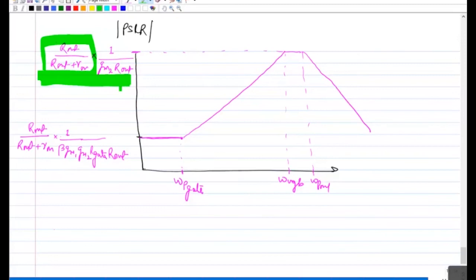And then on top of that, you have an inherent negative feedback from NMOS that will further suppress it. So your line transient is better, load transient is better, both line and load regulations are better, your bandwidth is higher. So all these benefits you get from the NMOS regulator.